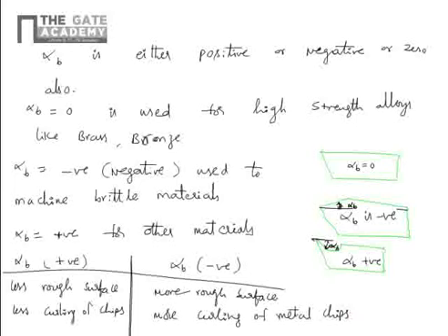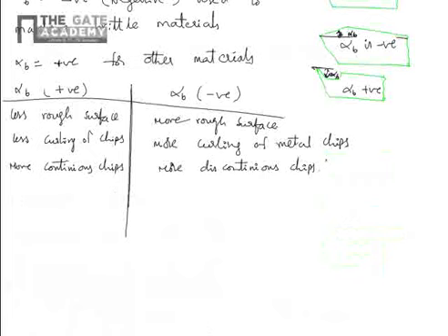Chips break, discontinuous chips. Here it promotes chip formation in positive rake angle, giving the tool more wedge shape but weakening the tool section, causing heat concentration near the chip and reducing the tool life.